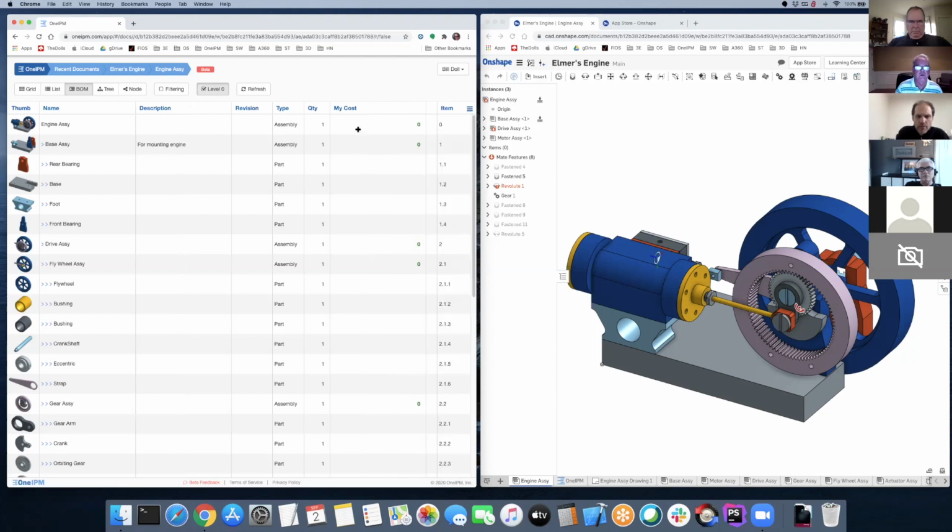That particular property, I can tell in Onshape that it's a floating variable, so it's numeric. So because I know that it's numeric, what I'm going to do when you're in this BOM type view is I know what all the sub-assemblies are and how they're put together, as well as the top level assembly and the quantities. So you notice for a lot of these, they have a green 0. That's because those are auto-calculated for you.